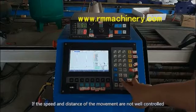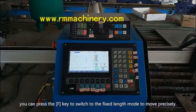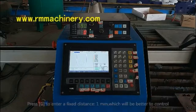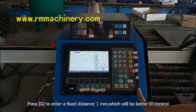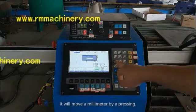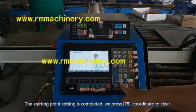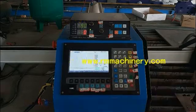If the speed and distance of the movement are not well controlled, you can press the F key to switch to the fixed length mode to move precisely. We move to the approximate position first. Press G to enter a fixed distance of 1 mm, which is better to control. It will move a millimeter with each press. The starting point setting is completed. We press F8 coordinate to clear. OK, then we cut.